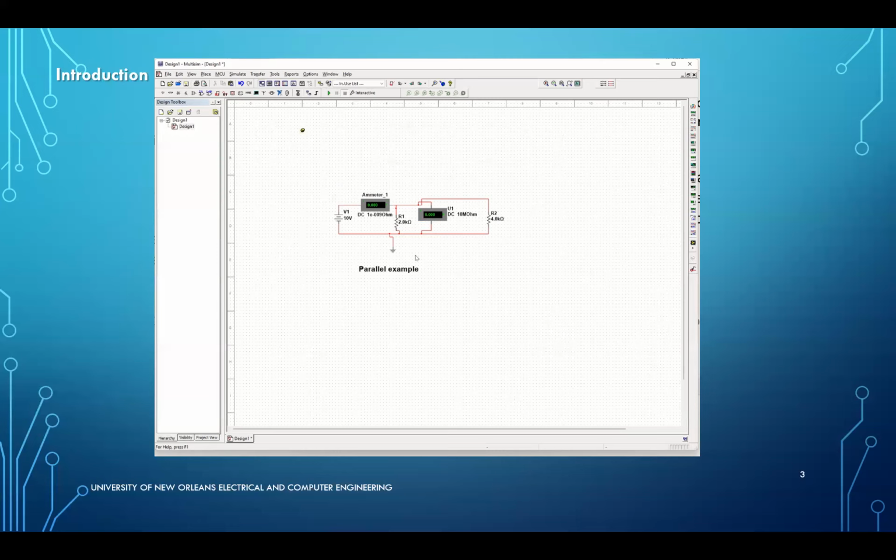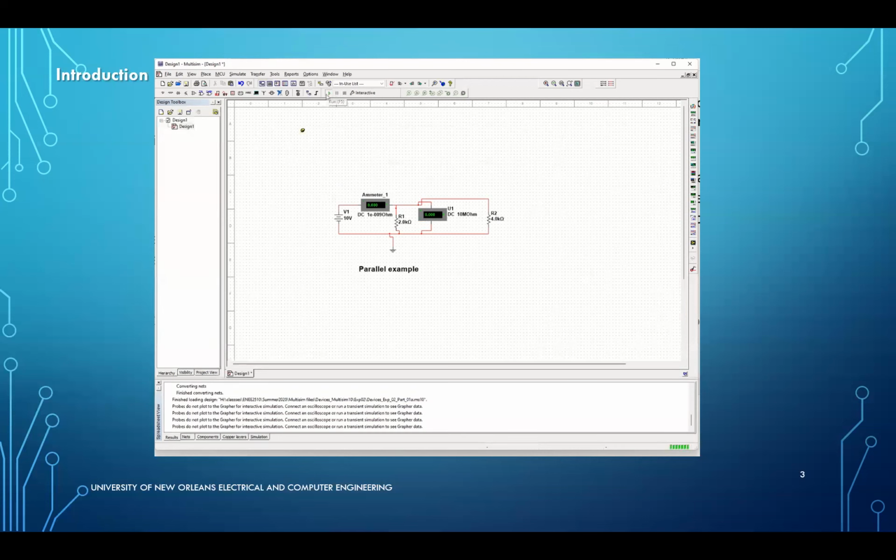And all I need to do now is just simply click on this run button, the green button here. It says run, and if I click on run, it's going to just take the measurements. As you can see, it's measuring 10 volts, right, as we know, across R1, R2, with a current of 7.5 milliamps, which it should be, right, because of the combination. By the way, you can also measure resistance, I'll show you in a minute. So that's how easy you can do this.